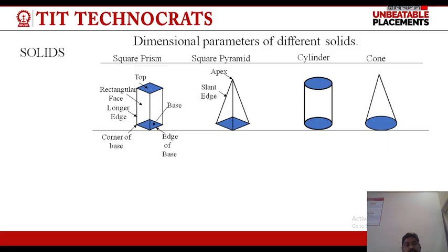A polyhedron is defined as a solid bounded by planes called faces. When all of the faces are equal and regular, the polyhedron is said to be regular. The next one is the tetrahedron. A tetrahedron has four equal faces, each an equilateral triangle. A cube has six faces, all squares. Now the next one is the octahedron.